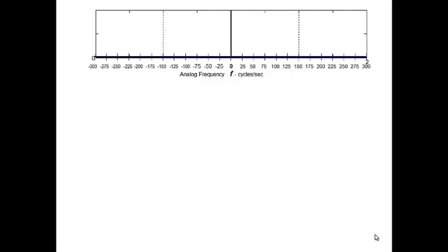And this is actually a convenient form for me to do the Fourier transform on, so we can see what its spectrum looks like. So this is the spectrum of our continuous time signal. Now, we haven't sampled it yet. We don't know that it's going to alias, but we'll start seeing that. All we've done is some trigonometric and mathematical manipulations. So nothing physical has happened yet. Just lots of different ways to write the same signal. Everybody okay with all those steps?